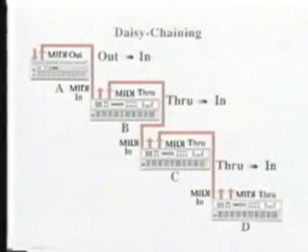Let's say we have MIDI controller A and 3 MIDI synths, B, C, and D. Each synth has its own keyboard and sound source. Now the basic rules of MIDI say always connect a MIDI out to a MIDI in, or always connect a MIDI through to a MIDI in. If you are playing the master controller and want to get to all of these devices simultaneously, connect its MIDI out to MIDI in. From here, it's MIDI through to MIDI in, through to in, and so on.